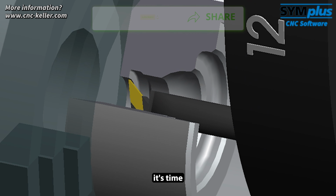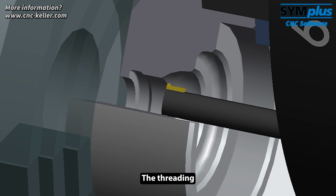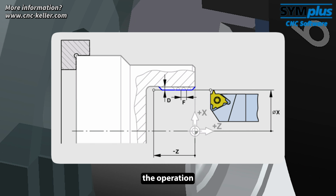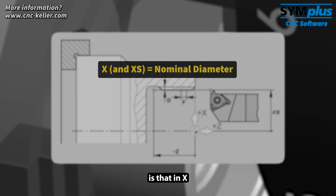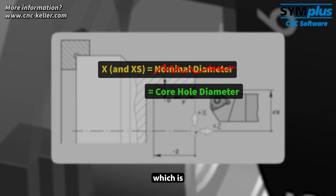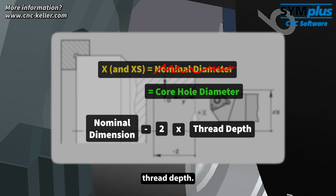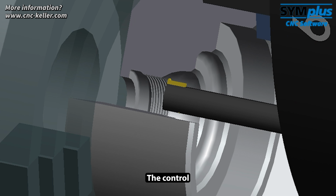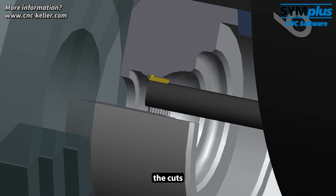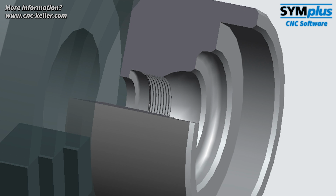After that, it's time for the internal thread, a classic exam task. The threading cycle G31 performs the operation in multiple passes. The key point here is that in X we don't enter the nominal diameter, but the core hole diameter, which is calculated as the nominal size minus 2 times thread depth. Pitch and thread depth are specified in the reference tables. The control automatically distributes the cuts across several passes until the thread is complete.